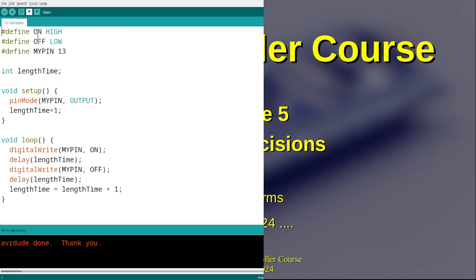Okay, and I've defined those, and I run that, and I try it out. You've noticed by now that we don't have to put the test 1 through first. We can just compile and run straight away. So we don't have to use the one that checks to see that everything's hunky-dory. We can just push that one and it compiles it and stores it on the Nano. So make sure your Nano is connected with your USB-C to your computer, and click upload.